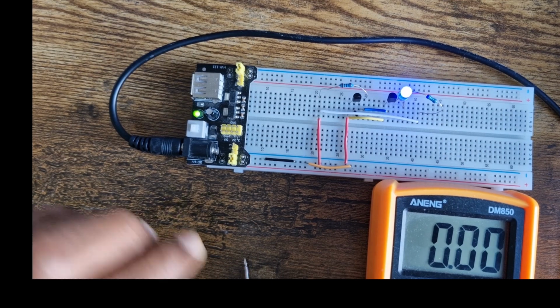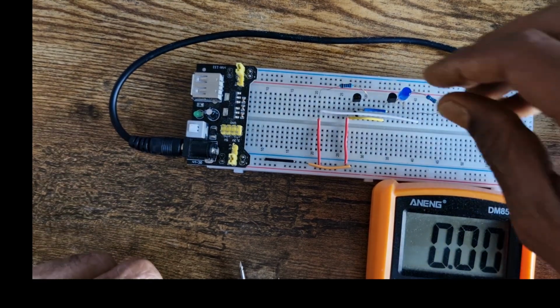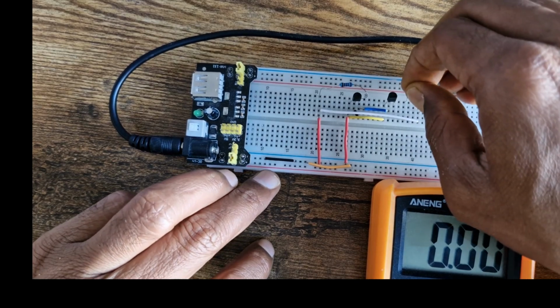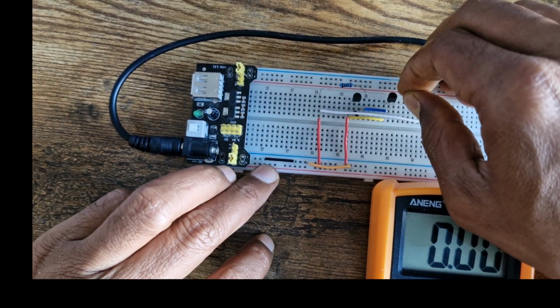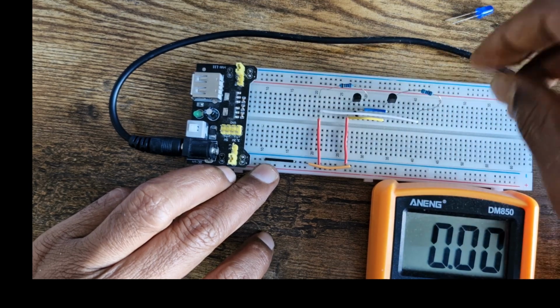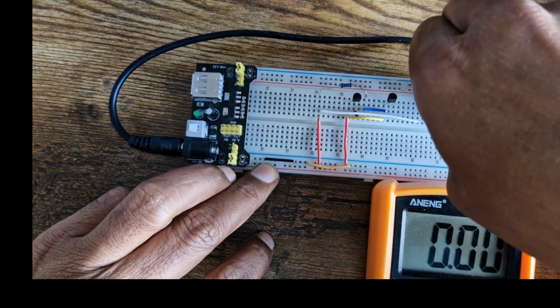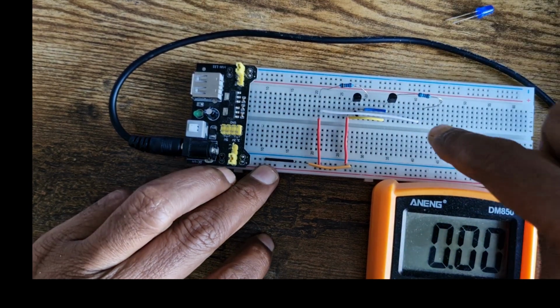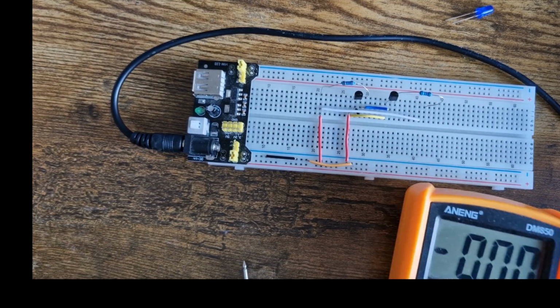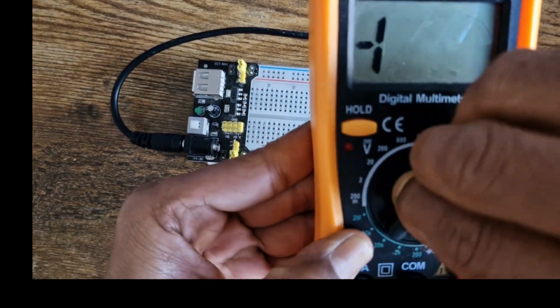So for example, switch it off here first, remove the LED, and instead just have this resistor connected to the collector pin, then break this point of the circuit so that emitter can be put in there. Now set the meter to the emitter range.